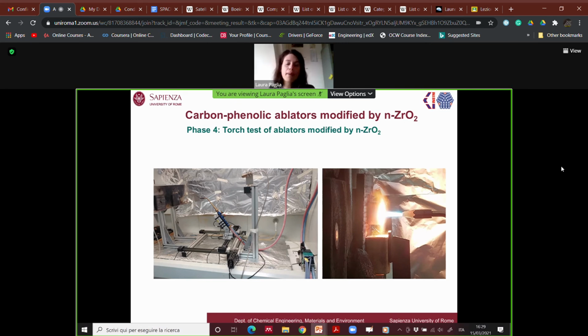I want to remind you that when we perform an oxyacetylene flame test, we cannot reproduce the condition of air entry, okay? But we can have a useful screening for the ablative material we manufactured.